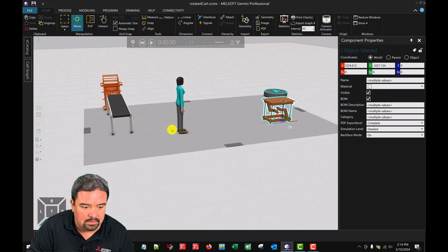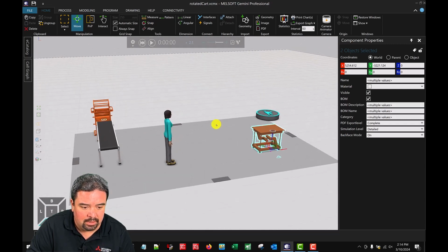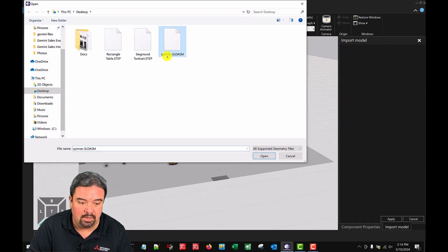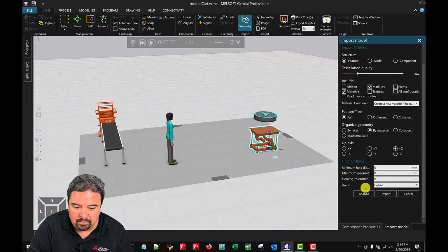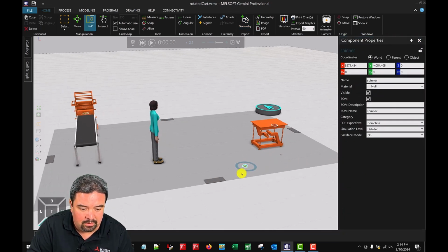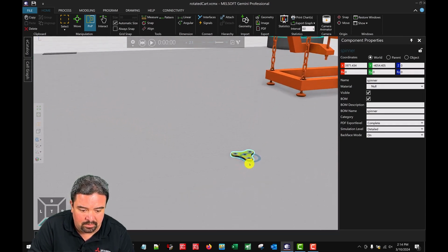So now what we need to do is actually tell her to go pick these up. But we may want to not just have a generic cylinder object, maybe we want something specific. So I've also downloaded an object. So let's go to geometry and let's click on spinner. Now this is a SolidWorks assembly, so yet a different file, but it will import the same way. So we say open and analyze 200,000 triangles on low. That's fine, we're just gonna leave it. We'll hit import, and now we have a little fidget spinner if we zoom all the way in.